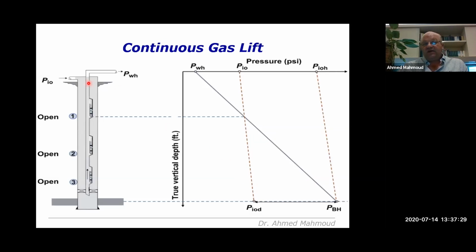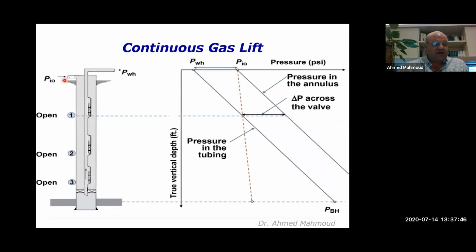We will start with a case of a well. Typically the well will have liquid both inside the annulus and inside the tubing. We start with step one, pressuring up or injecting gas in the annulus. Once we start injecting, the displacement process starts, and the fluid is pushed from the annulus into the tubing.